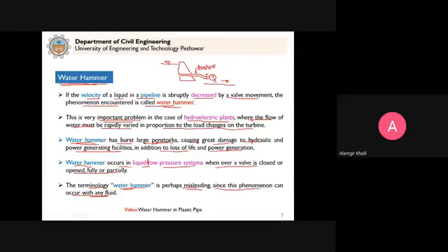This is because we have forms of energy. The water is flowing with these forms of energy: it has the velocity head, it has the datum, and it has the pressure head. Now when you make the velocity 0, then between the two sections, Z is the same for a horizontal pipe, so we ignore this. Where will the energy go?